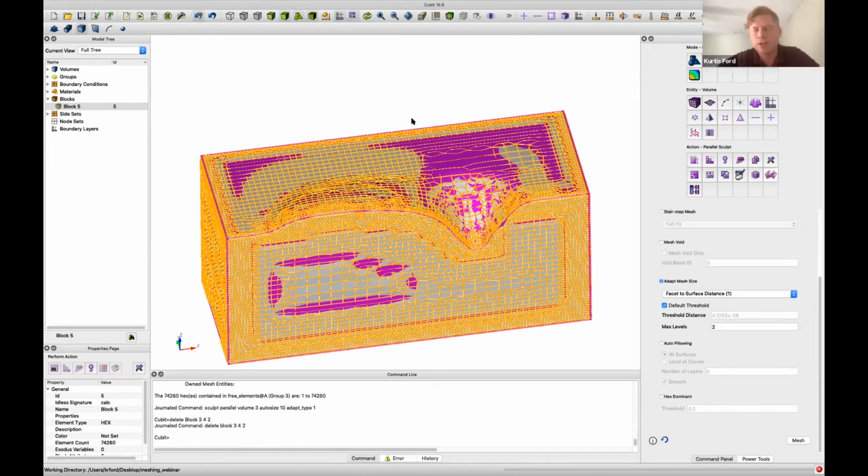Okay, I said this in passing, it's an entire conversation. There is technology that allows you to use TET meshes on a plastic problem like this, because we're going to use a viscoplastic material model for the metal. And there are technologies like the composite TET that you can use. There are some trade-offs to them, but in this particular case, what I was showing in the beginning is the quality of the TET element was so low that those TETs would invert.